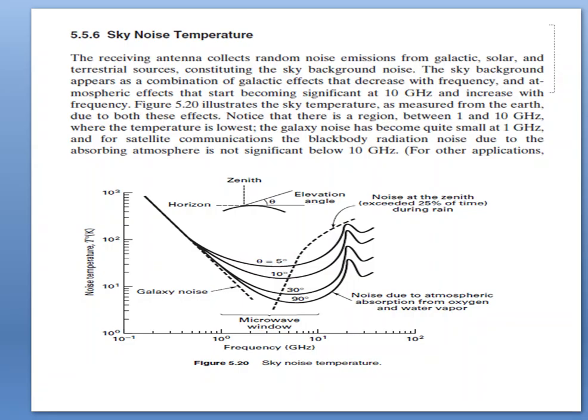As a reference figure, here is a radio map at 600 MHz. The galactic noise is reduced at this higher frequency compared with the figure below, with a low of 8 K and a high of 290 K. If you are examining these figures for the region of greatest noise radiation, where on each map do you see it most actively?